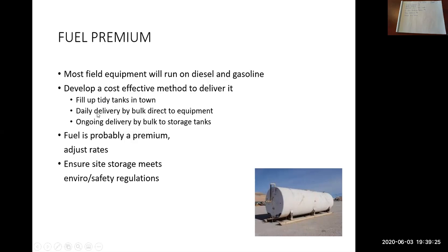Another option is daily delivery by bulk carrier. So the big fuel trucks come to your job site and they fuel your equipment up. That's a very good option. All you have to do is call them and they'll show up that night or the next morning and fuel everything up. If that's available, that's a very good option.